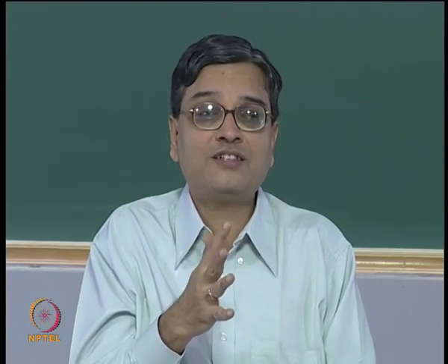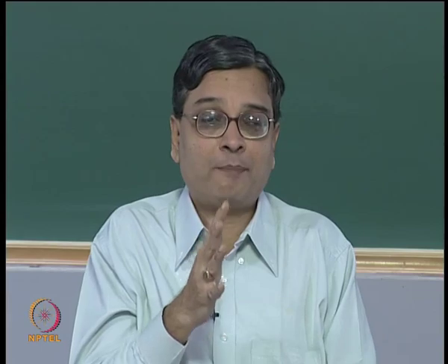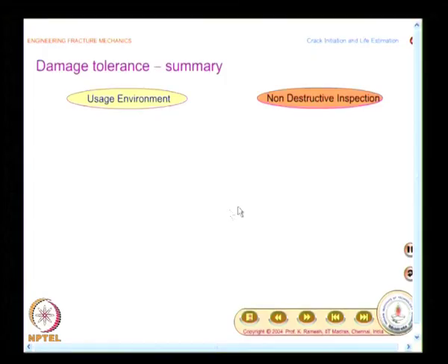So, all that requires careful data collection and analysis and then establishing inspection intervals, because the inspection intervals have to be realistic. If they are not realistic, fracture mechanics is not going to help. You have to apply fracture mechanics concepts very, very carefully.